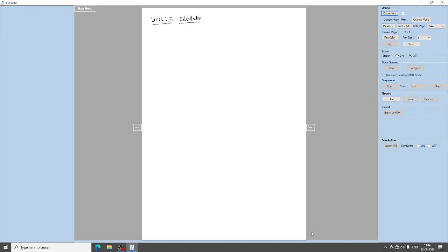To analyze the basic concept of oscillators, we have to start with the feedback model. Okay. So in the feedback model, we have a mixer and an amplifier circuit which is represented by a certain transfer function. So we have a feedback with unity, this is the input X of s and output Y of s. Okay. So this is the feedback circuit that we have.